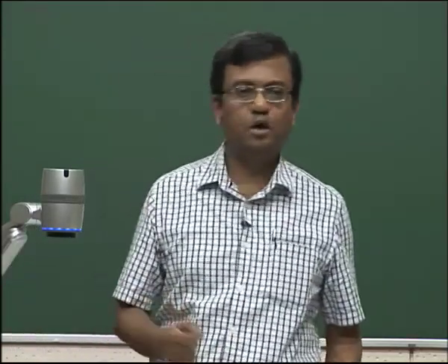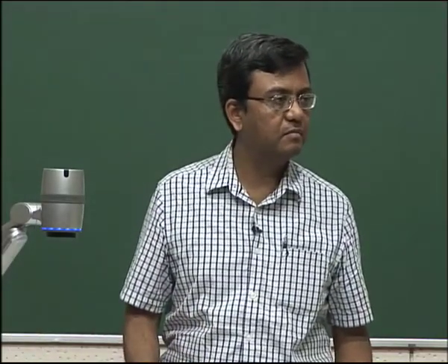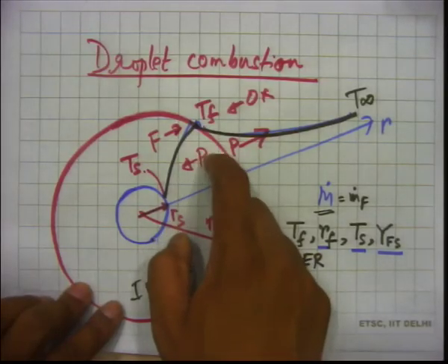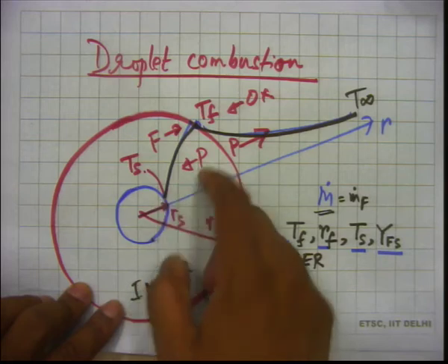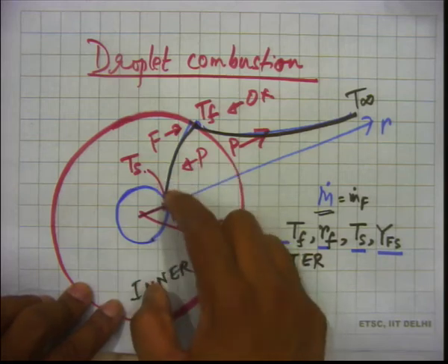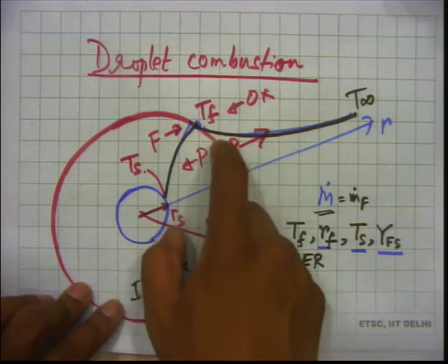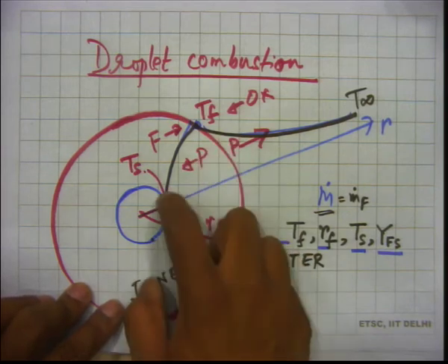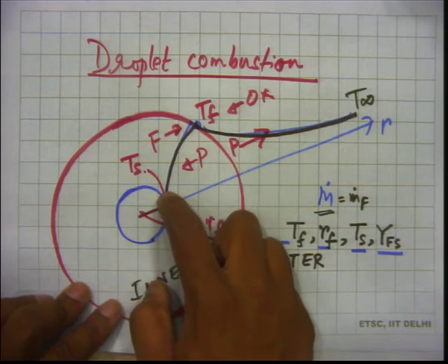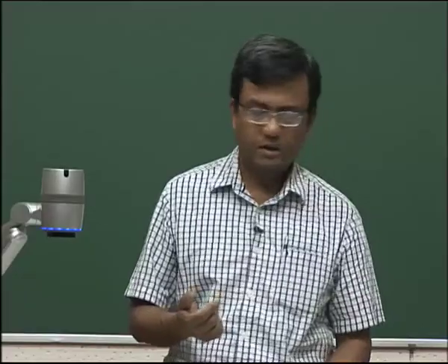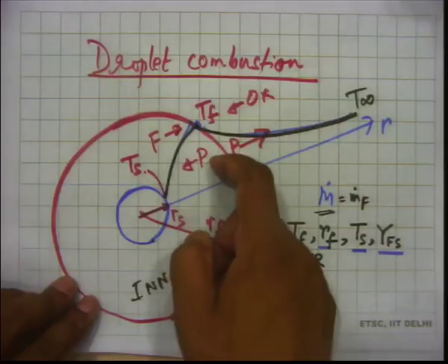If they do not get dissolved in the liquid fuel, then they are produced here, but they will just establish a product mass fraction profile: higher value at the flame, smaller value at the droplet surface, but there will not be a net flow of products into the droplet.